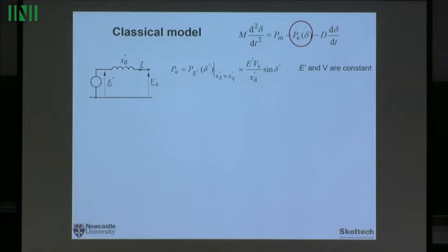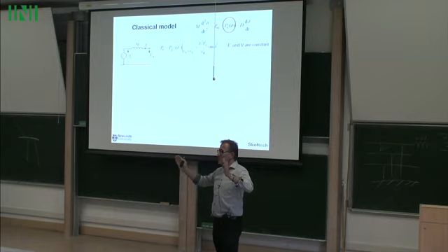So this is the equation: PE is equal to E' times Vs divided by the transient reactance, multiplied by the sine of the angle delta. The dash signifies that it is the transient state. And this is the main model used for transient stability analysis, which is a few seconds, because if you talk about losing stability, it will happen over 2 or 3 seconds.